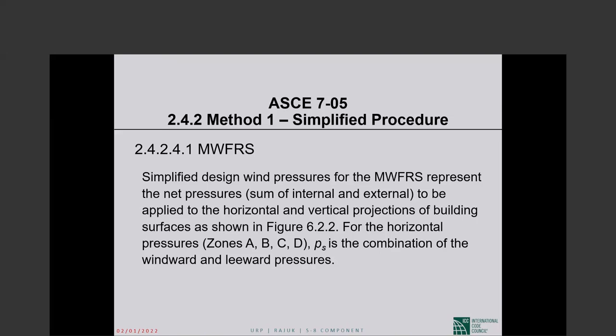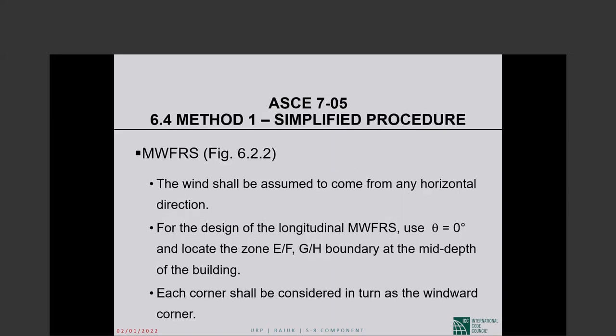So on the roof, it would be net sum of internal and external pressure. Okay, so what is said here is very, very important, and I hope you are following. So horizontal, it is all you apply on the building, the sum of the pressure on the windward face and the suction on the leeward face. The internal pressure doesn't count, it cancels out. But roof, it is the external suction minus the internal pressure of suction. Okay. The net value is given.